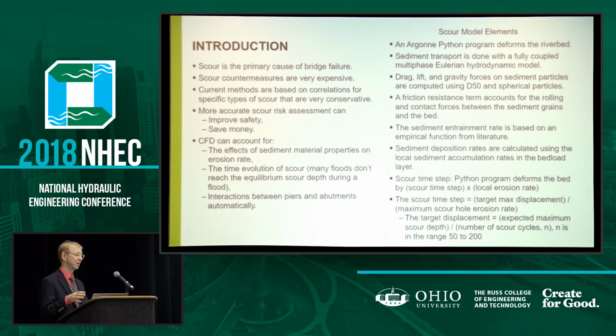So when we start going, the sediment gets entrained. It'll be convected downstream, and it'll settle out. Some of it will go out the exit. So we monitor that, and when our entrainment rate balances the mass that's settling and going out, then we decide that that cycle is good and done, and we go to this external program to deform the bed.